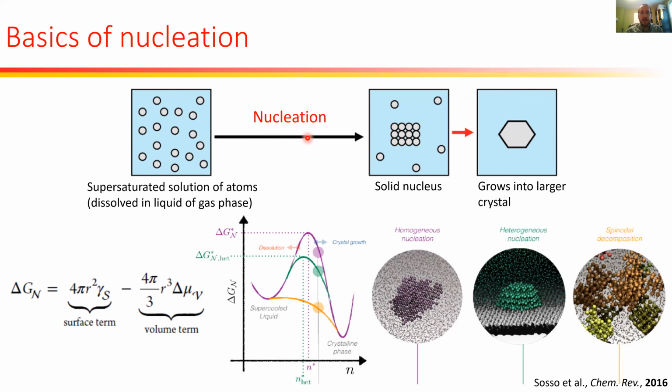And right, there's a thermodynamic driving force for nucleation to happen. However, there's a kinetic barrier for this to occur as well. And that's because we need to create new solid-liquid interface. And this gives us an unfavorable increase in the Gibbs free energy of the system, while forming just a new bulk solid is thermodynamically favorable.